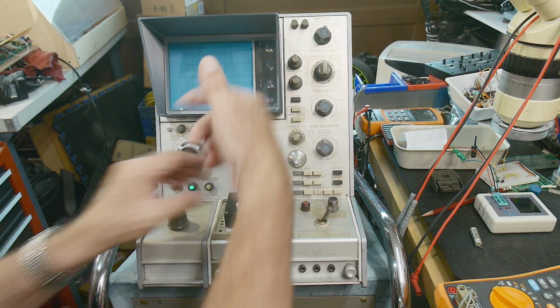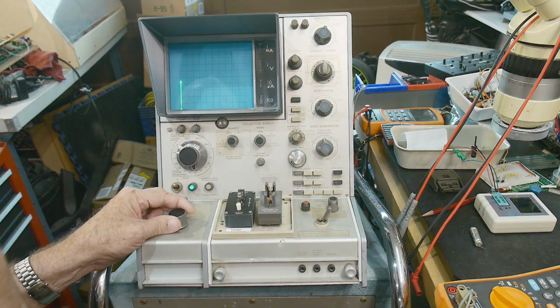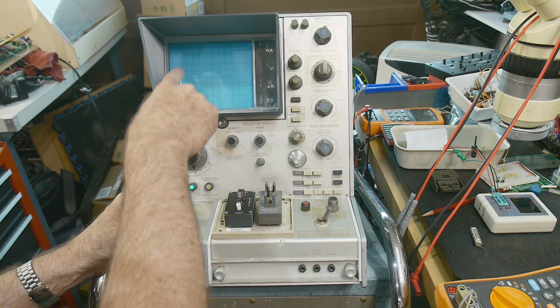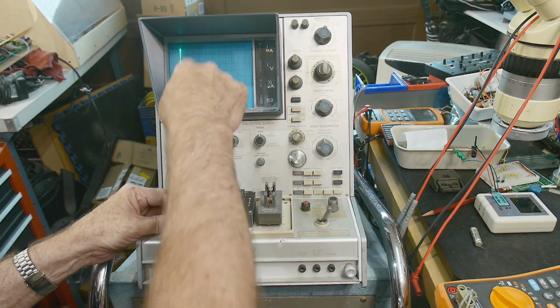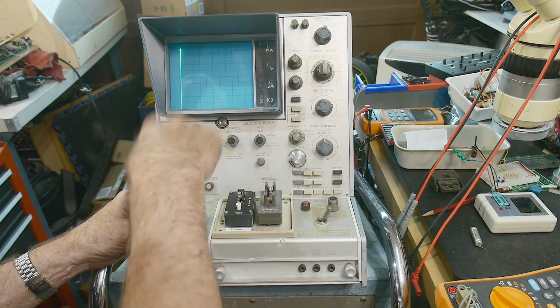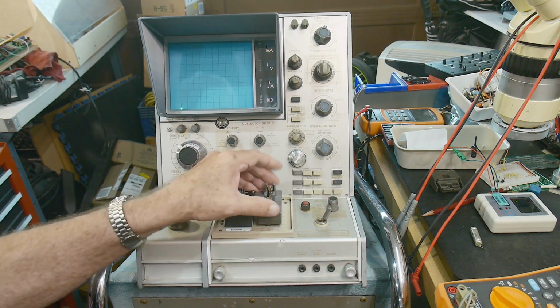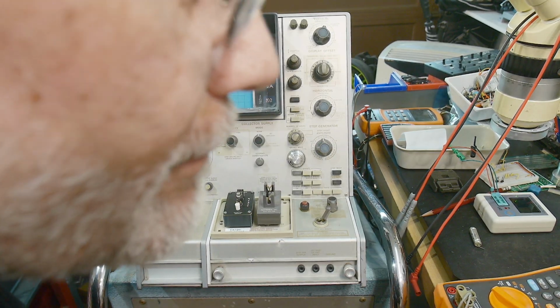And then as I turn it on, the current will go up, and I can set it to sweep between 0 current and 5 milliamps, 0 to 5 milliamps, or 0 to 10 milliamps, right? It's sweeping because it's seeing a dead short, so it's only sweeping as far as I'm allowing it to sweep, okay? All right, so that's the way that works. Now, what if I put in a resistor, okay?